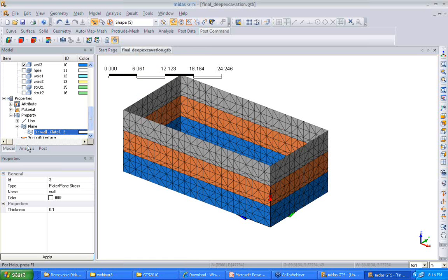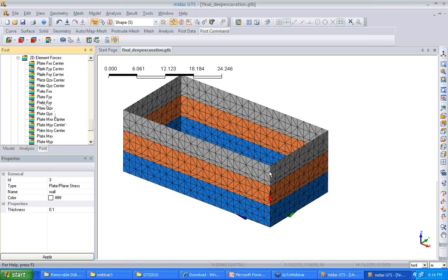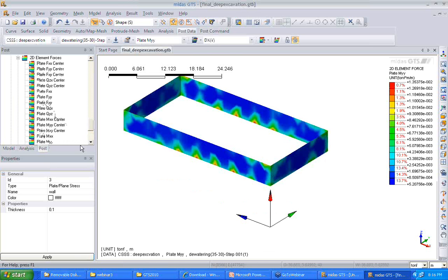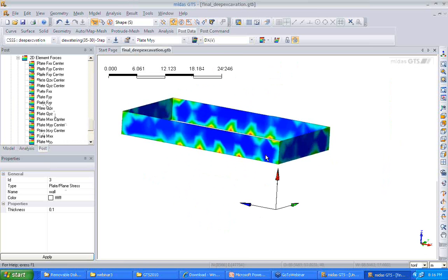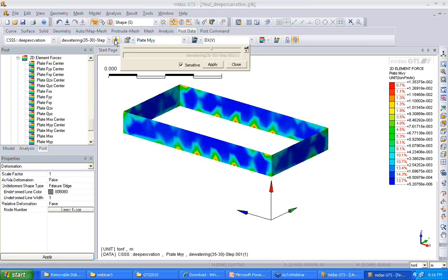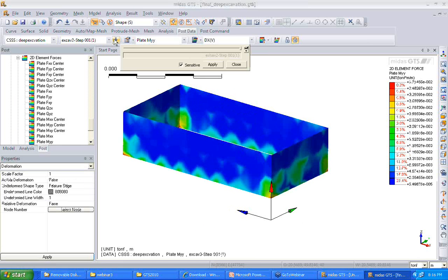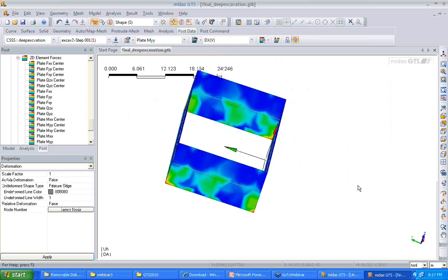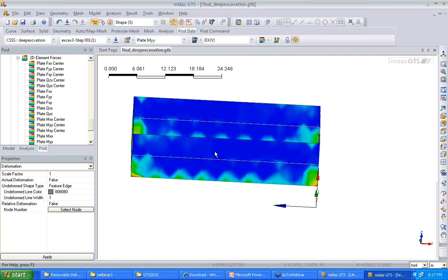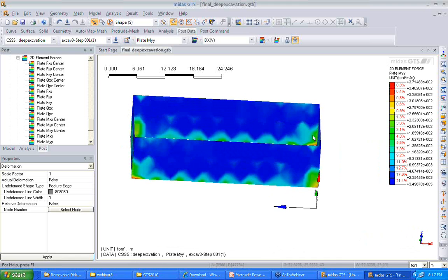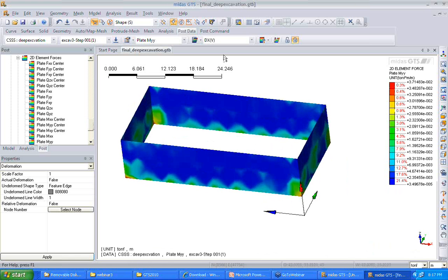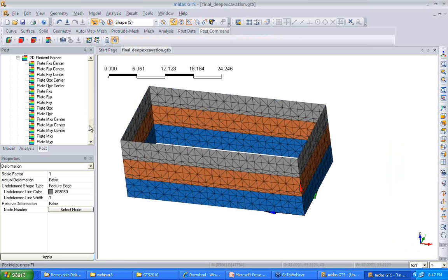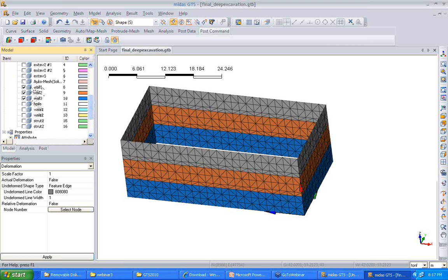Okay, now let's see the results. After this has been done, the results carry some value. Previously, this is how we extract the accurate amount of information from the millions of elements containing information. These are the values of the bending moments of the plate. Next in the list we have 1D elements, which are mainly piles, struts, and wales. So first I will be considering just the pile elements.